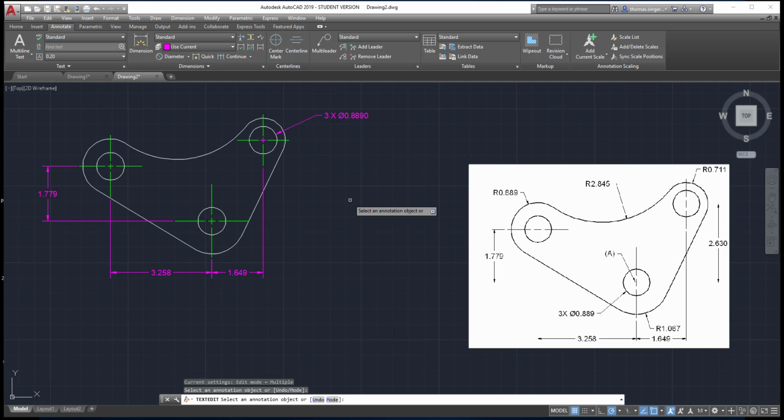All right. The last thing I wanted to show you is how to put this on a layout. And so that way the drawing can be printed or create a PDF of that drawing for output. So under layout number, and we have 2 layouts, 1 and 2. Makes no difference which one you choose. We're going to choose layout 1.